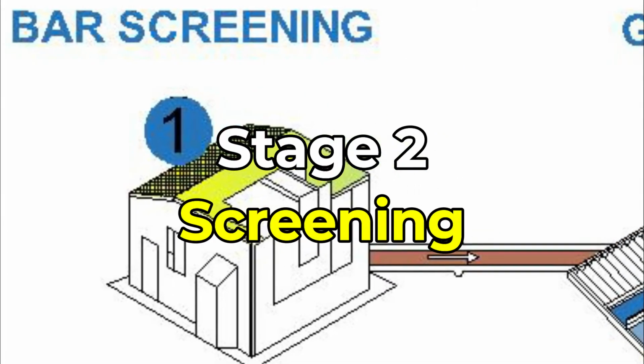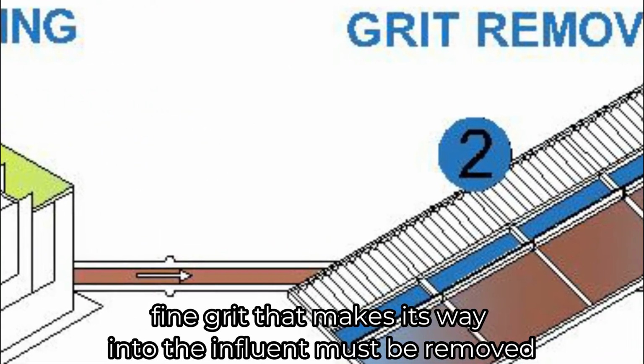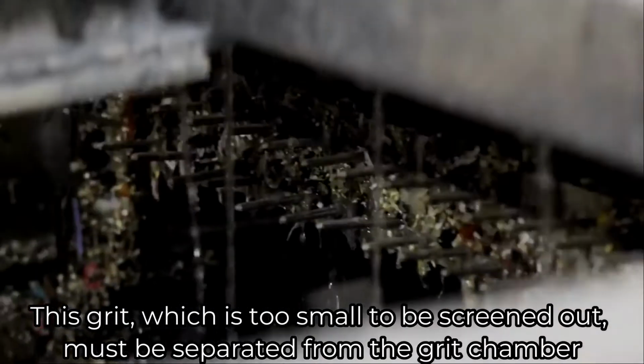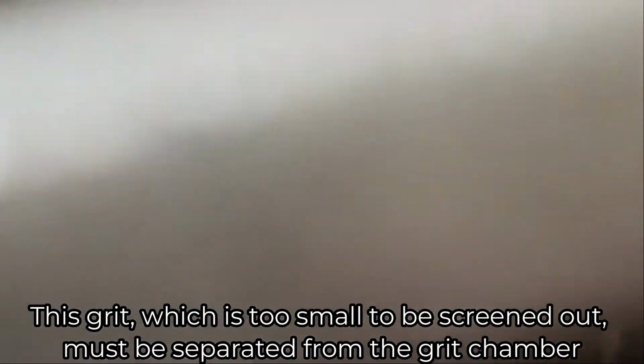Stage 2, screening. To avoid damage to pumps and machinery downstream, fine grit that makes its way into the effluent must be removed. This grit, which is too small to be screened out, must be separated in the grit chamber.